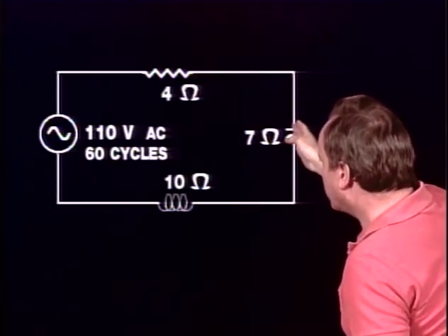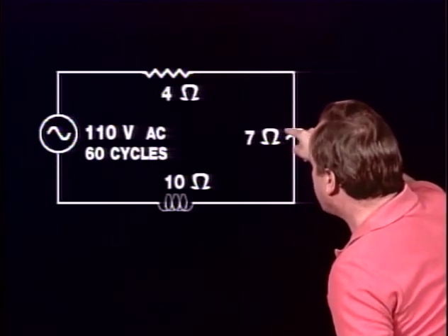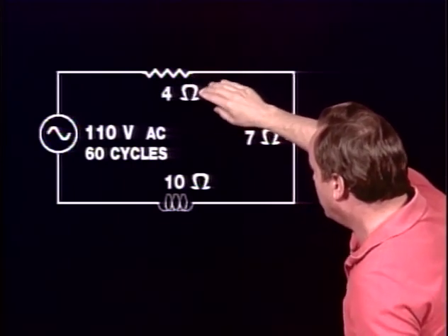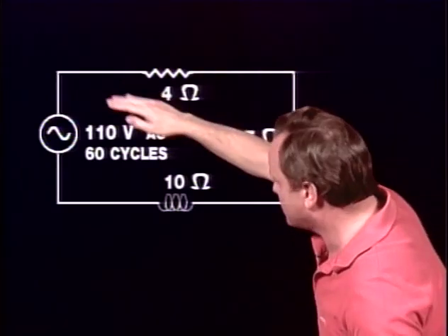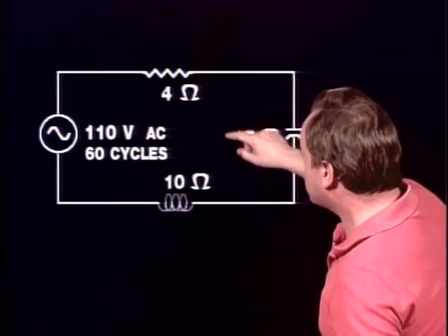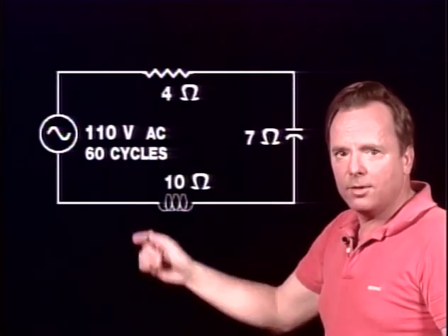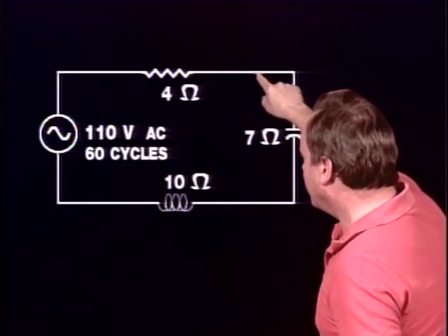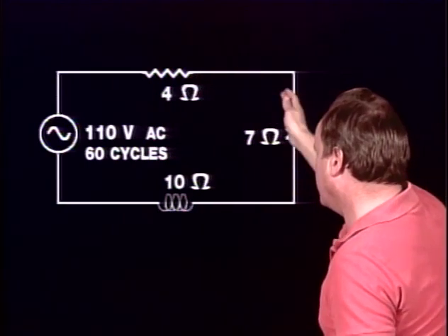But if it's alternating current, the current tends to reverse in direction, and then what happens is the capacitor gives up its charge right away. And so then the current will flow back this way, charge the capacitor, then it gives up its charge when the current's going back. So this capacitor also tends to impede the flow of current. You can see that when you have direct current, the impedance is absolute. It just completely stops the current going through here.